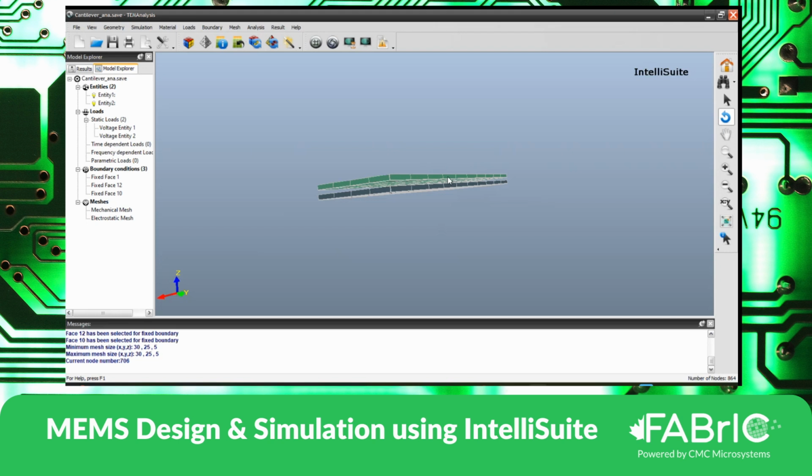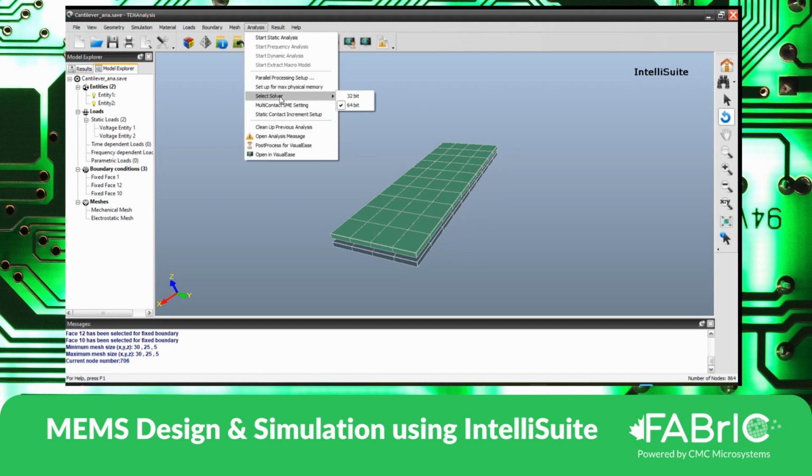Now, the bottom layer is a fixed geometry. It does not participate in any of the physical movement of the device. It's die attached. So why do you want to create elements on such geometries which are fixed, which are not allowed to move? So this will help in reducing the number of elements for the computation for better analysis, or faster analysis, to be more precise.